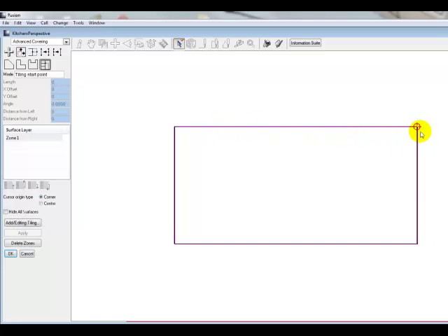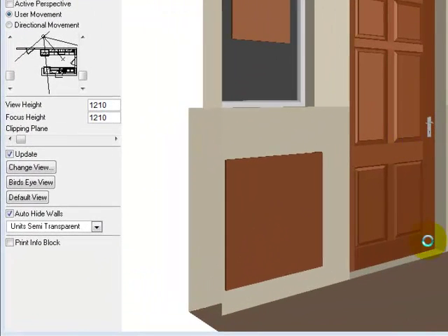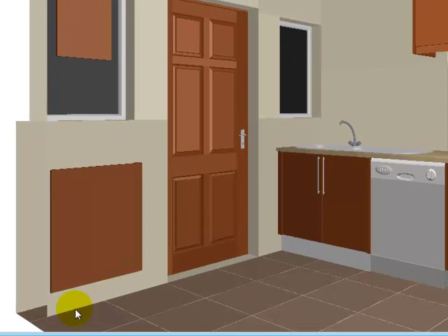When highlighting in red, we'll be able to take our little start point icon and move it over to the furthermost point of our floor, and in order to have it started on that wall, we'll need to offset it 200 millimeters in. So we just drag it, and we'll notice that our X offset on the left hand side over here is going into the minus values. So we just type in minus 200, press enter on our keyboard, and now when we go back to our perspective view and it generates our preview, we'll see that the tiling now starts on the edge of that wall.